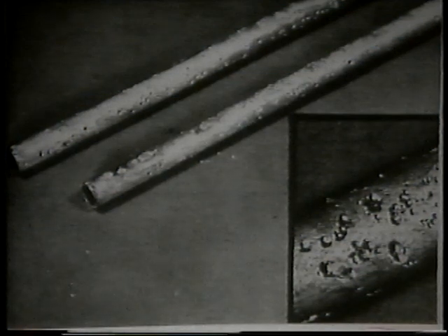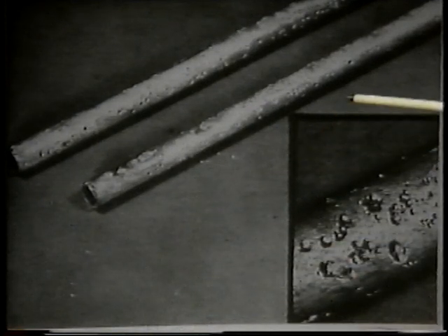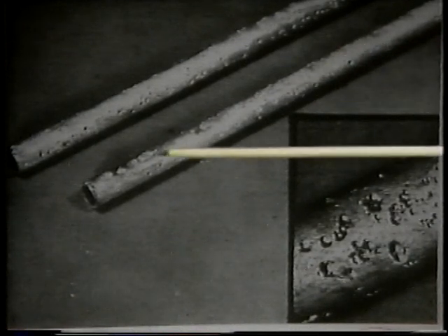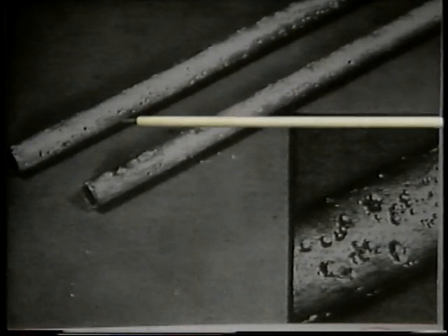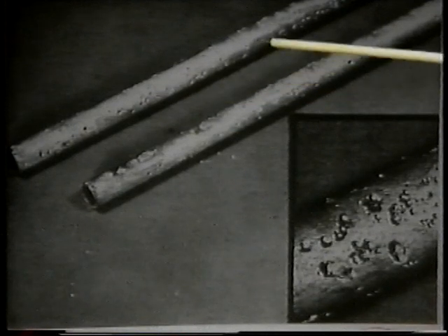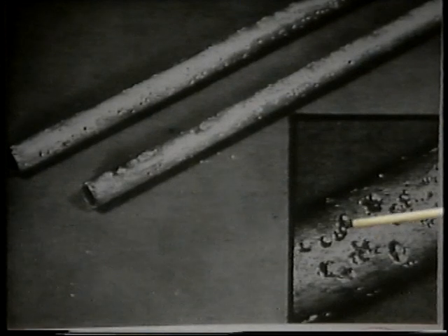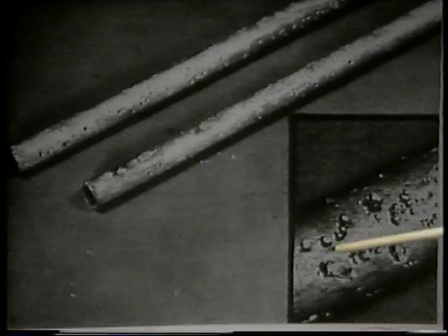The other aspect of marine corrosion, if we're talking about the corrosion behavior of stainless steel and other materials that depend upon their passive film, is that chloride ion can be very aggressive. This is an example of some stainless steel rods. You can see the multiple pits along that rod after it's been exposed to seawater. This is a higher magnification shot. You can see the amount of damage that's incurred here.